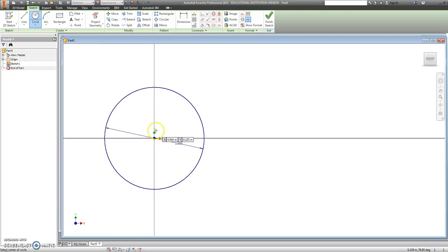So once I've made this circle, the next thing I want to do is add a center line. So I'm going to come up here to center line. I'm going to go just somewhere to the left of the circle that I've drawn. Click on the X axis, drag it. Nope, sorry, need to make sure I'm in center line. I didn't have the line indented. Once again, center line is still highlighted, so I'm going to click to the left, drag a center line